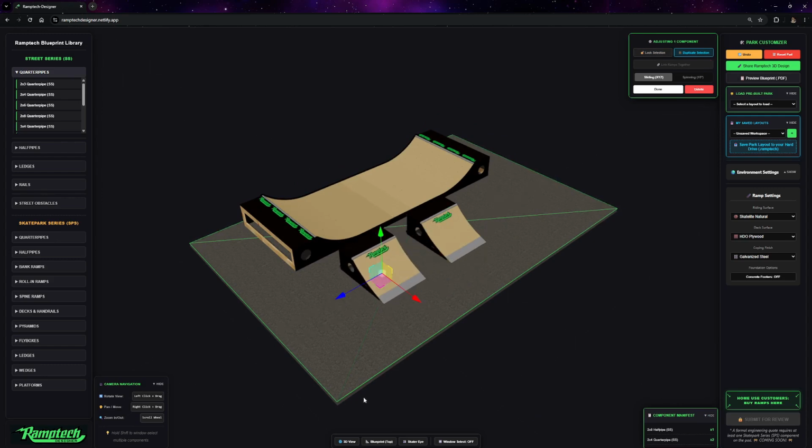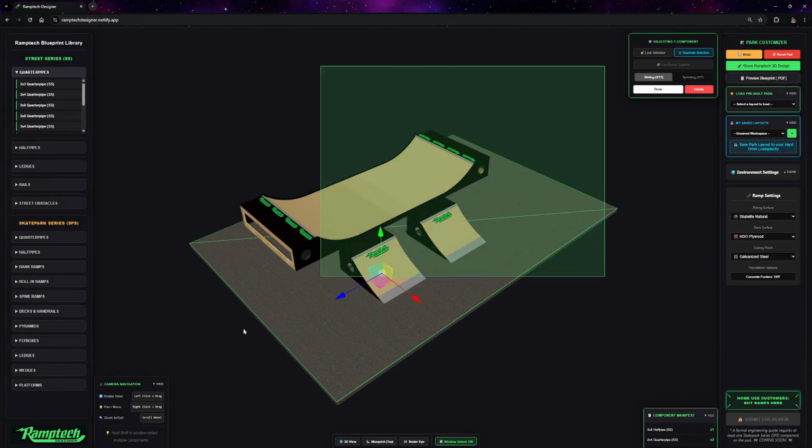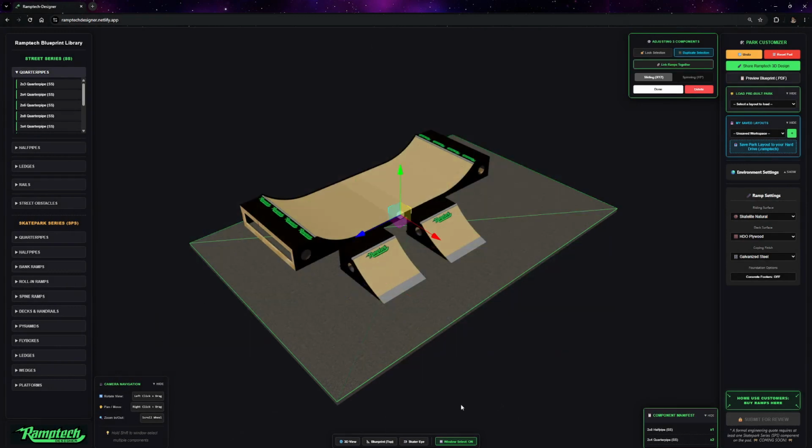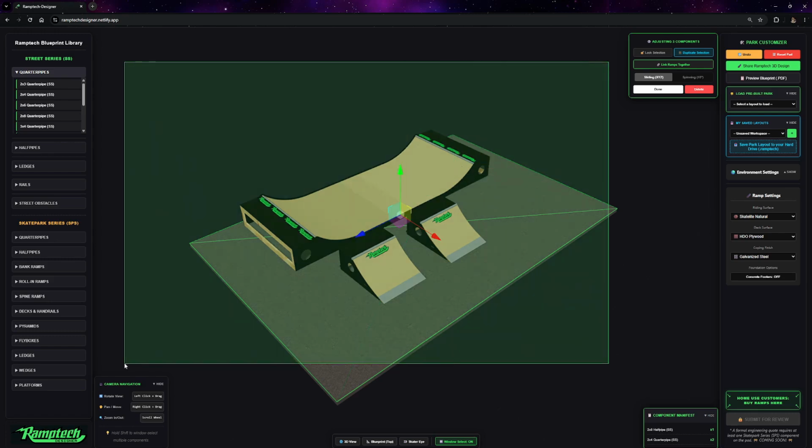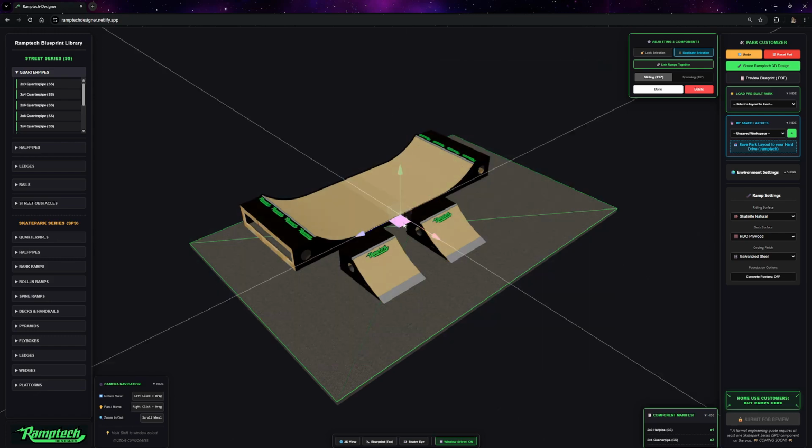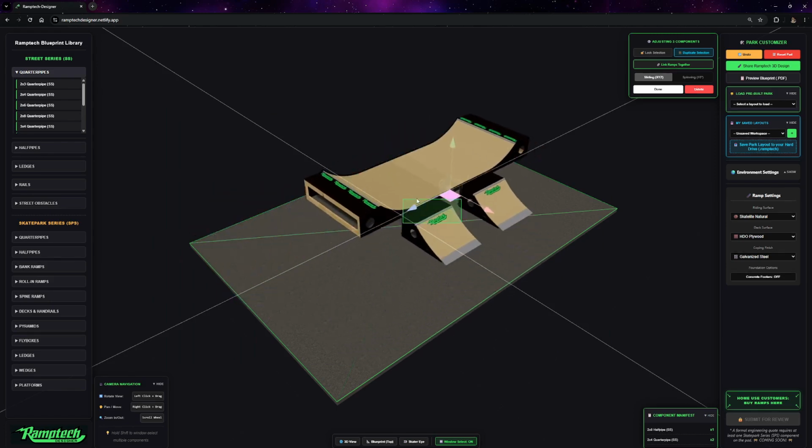Now you have the ability to window select. You can either click the window select button down here, which turns on the crossing window, so it's a click and drag. Window select is still on. I'm going to hold down left click. I'm going to drag the window around. I'm going to let go. It's selected everything, and now it's all moving as one unit.